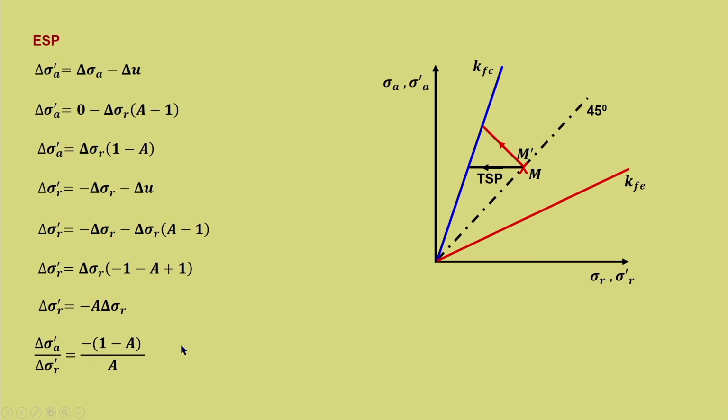Definitely it has impacted the determination of pore water pressure. The expressions were different, but the slope is going to be same. So, whatever be the manner in which the compression has been done or performed, the effective stress path slope is same.